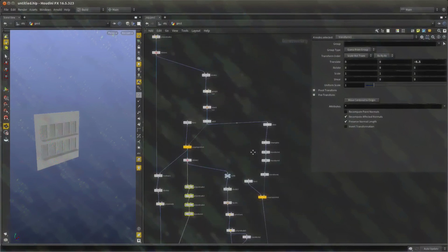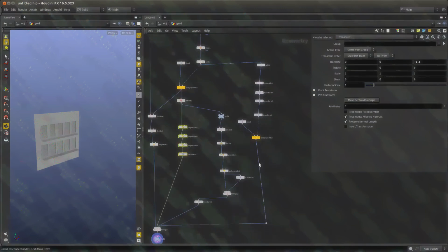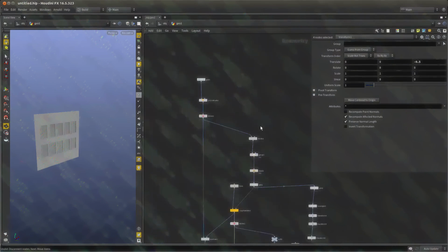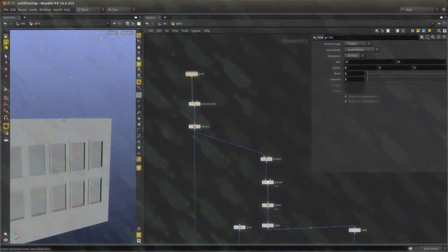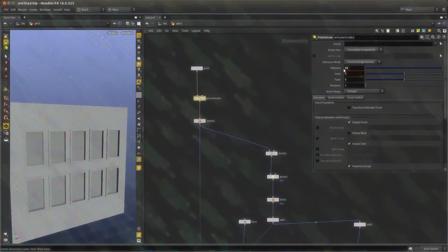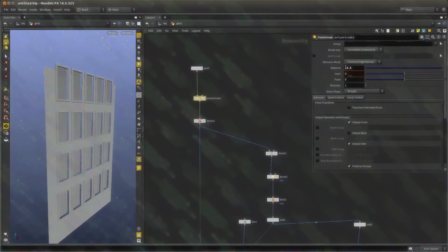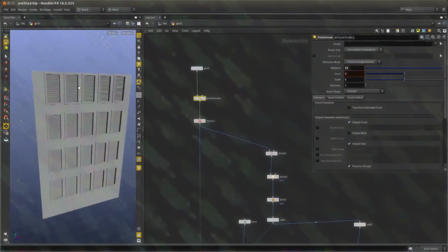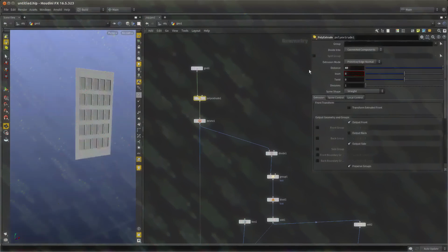And now that we have everything dynamic, I'm going to disconnect this, right click, disconnect. I don't want this section here. And I'll explain why in a second. And you saw that we've started off with this extrude node. We've based off everything from this guy, based on this extrude. So let's say we wanted to increase the extrude. Nice. So it's working. So every time we increase the count reasonably, it adds a new floor. Let's set it to 20. Cool. So let's set it to 40.